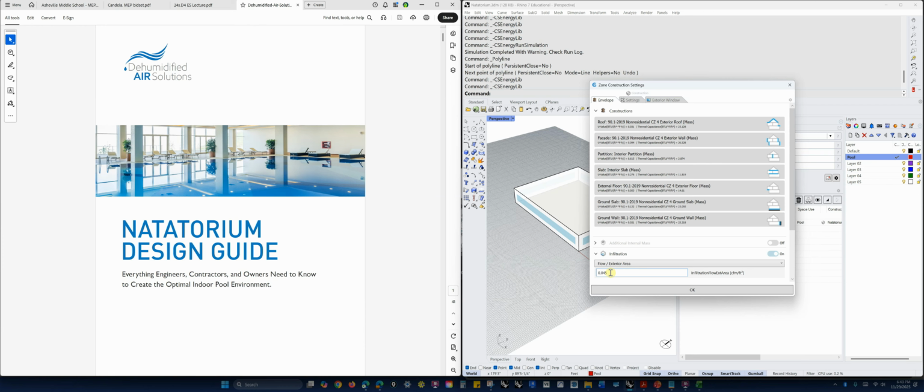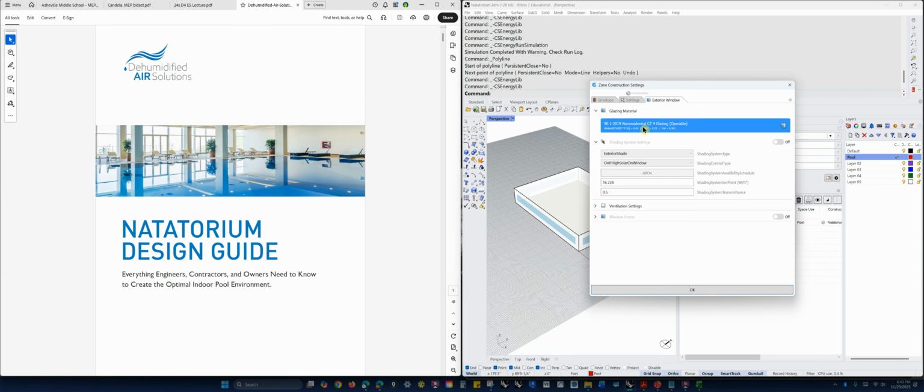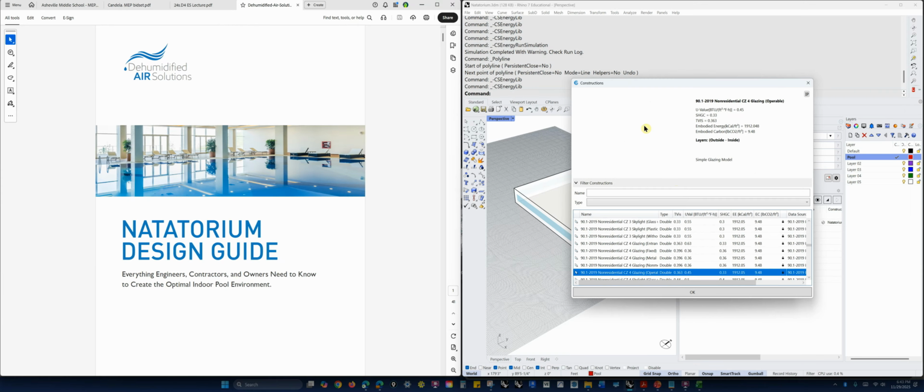We have no way to really set that in this simulation workflow that we're using. But air tightness at this level will be a good approximation of that, or would be helpful to that. Okay, then I set my exterior windows to be very energy efficient, partly because they'll also be very watertight.